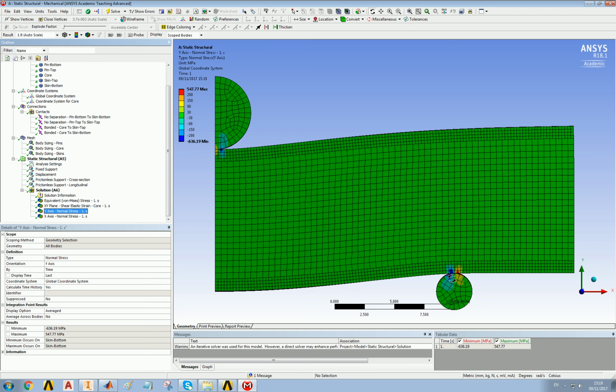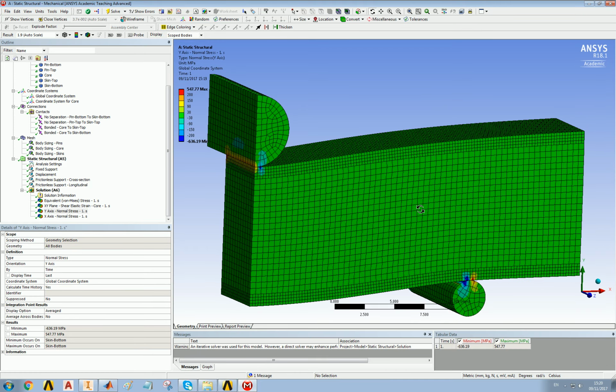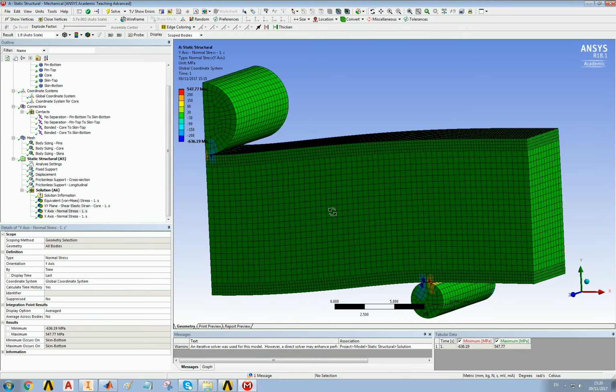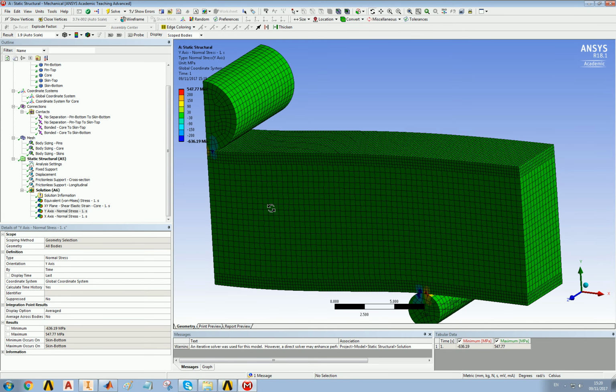The stresses that you see around here are actually wrong. You don't see that in a contact. That's basically saying there's a lot of high tension here. And as with the problem that we looked at with the hook, you don't see tension across contacting surfaces. You only see compression. You would expect to see a blue zone more or less where the blue zone is, but not to see the red zone there. There's a lot of tension here, so the contact here is slightly odd. But getting contacts right in ANSYS is always difficult, or indeed in any finite element package.